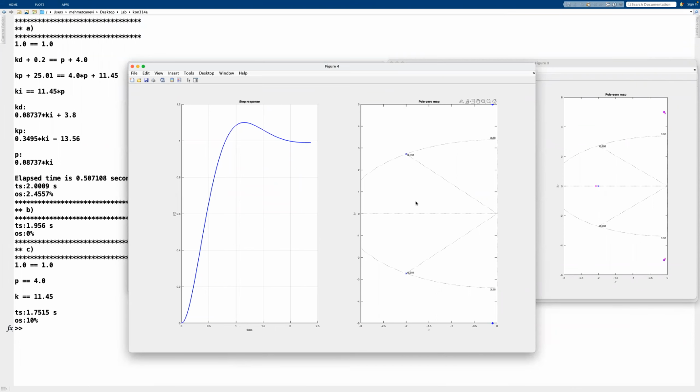We can see we have 2 poles here, and we can also see we have a pole zero cancellation exactly here. So technically we have 4 poles and 2 zeros, but a pole zero cancellation for a pole pair happens. Therefore, we end up with just pure 2 poles, and we choose these poles so that we have the settling time and overshoot requirements as we want them to be.